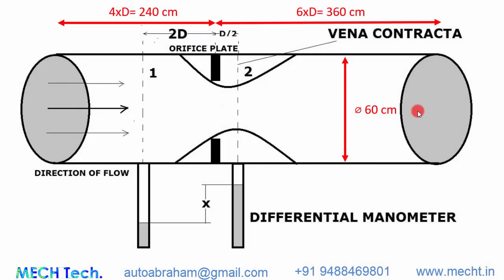This is the pipeline that we have selected for our analysis. Here we have to measure the pressures at 2 points, one at here and another at here. So this pressure difference will tell us the flow rate. In order to measure the pressures at that position exactly, we have to create a line at this particular place. So here the x distance is 120 centimeters and y distance is 0. Here this x distance is 120 centimeters, whereas the y distance is 60, because the diameter of this pipeline is 60, we have drawn this model exactly from the origin here. So here 0, 0 is there. So let's create this line in ANSYS Fluent to view the pressure result.